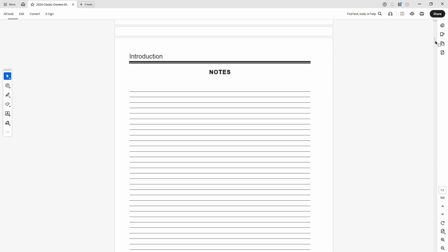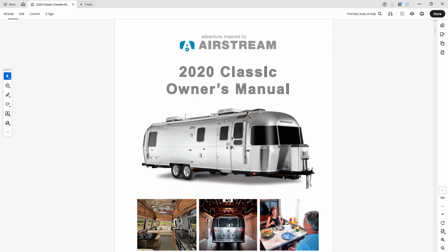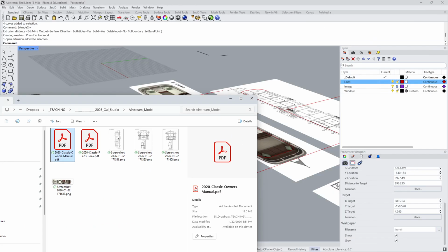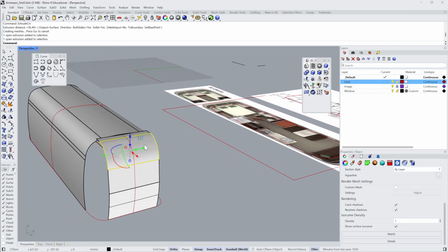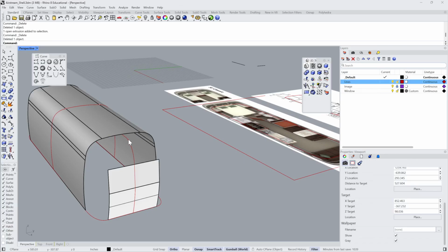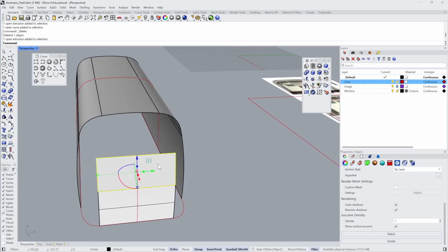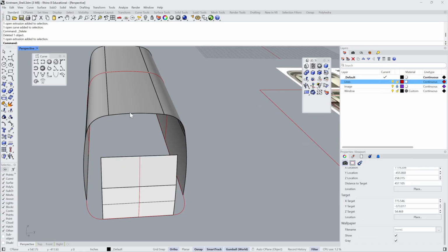And we're going to see that this is kind of curving down here, right? So we have double curvature here that we need to create. And this is where blend surface is going to work out really well. So I'm actually just going to delete these curves because they got us apart so far. The windshield is flat, so that's great. We can work with that.